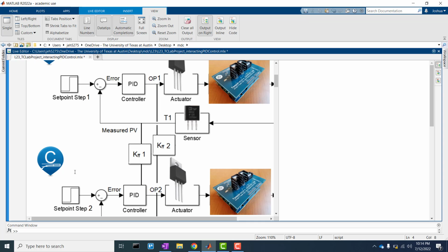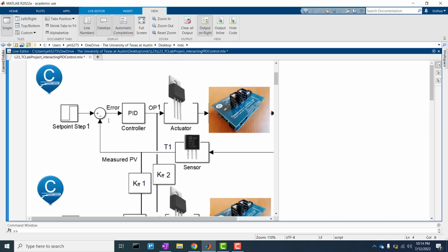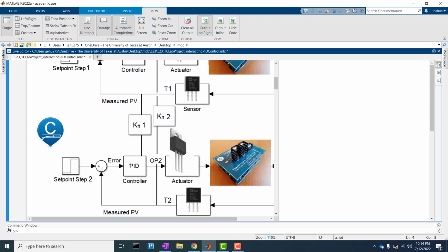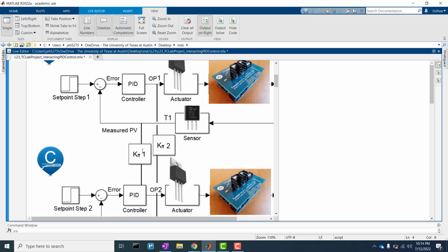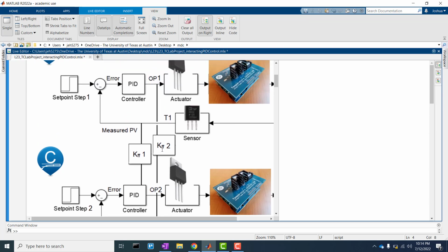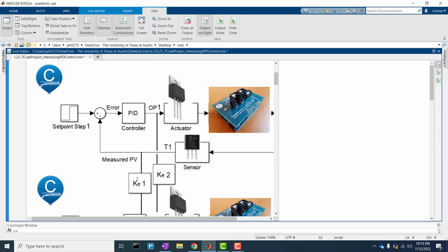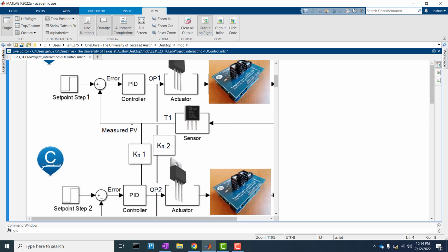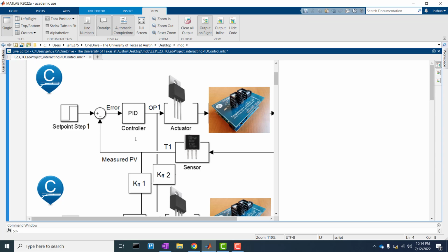and just show our system here, it has 2 set points where we compare the conditions, the measured PV, so the measured temperatures, and then we change our PID based on the delta temperature between what we want and what we have. With that feed-forward control, we will take into account first KFF1, which is the difference in the measured PVs, and then KFF2, which is the opposite. KFF1 will look at how 1 affects 2, and KFF2 will look at how 2 will affect 1 with the